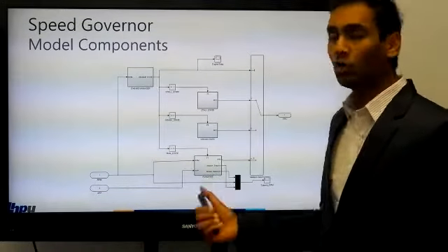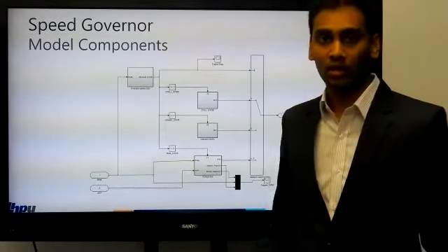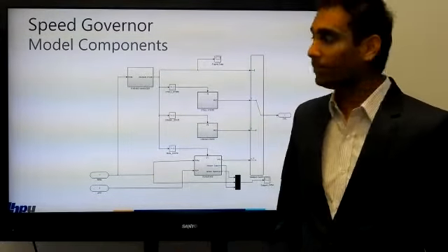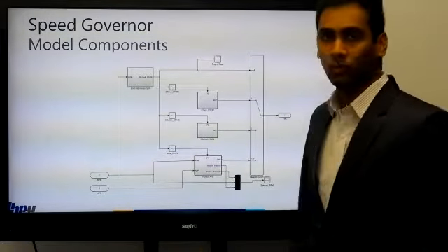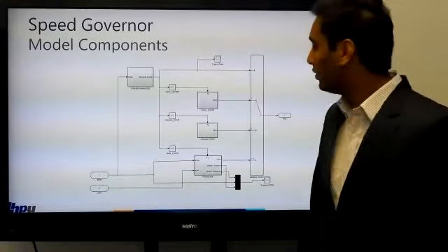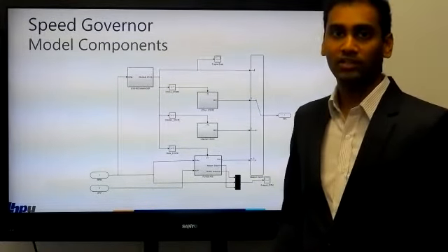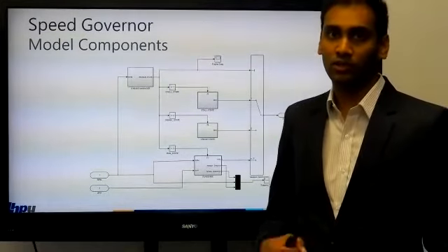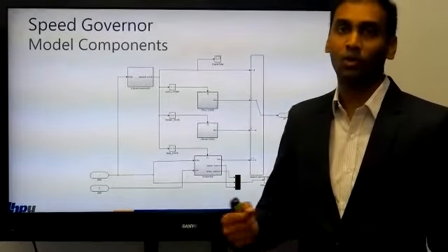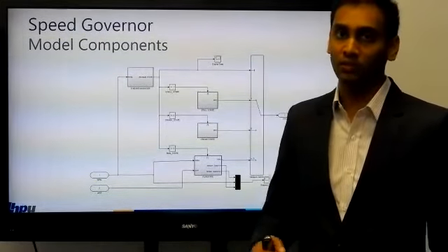So this is the whole model of our minimum and maximum governor. We do have an engine manager which says which state your engine is in. We have 3 different states of engines: stall, crank, and run. The stall state says that your engine is switched off. The crank state, your engine is switching on, and the run state says your engine is switched on.